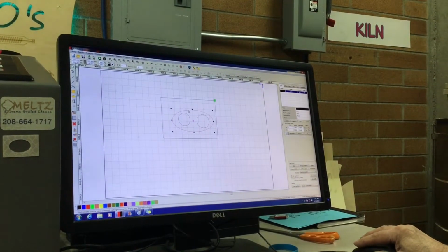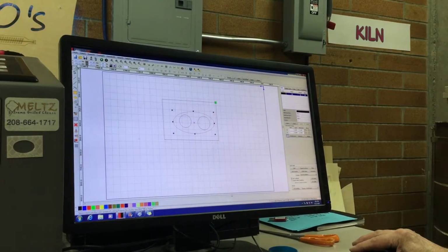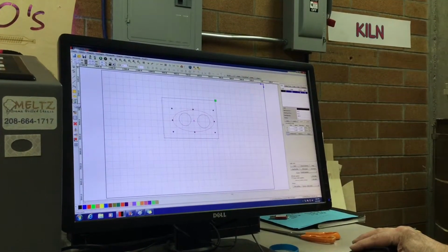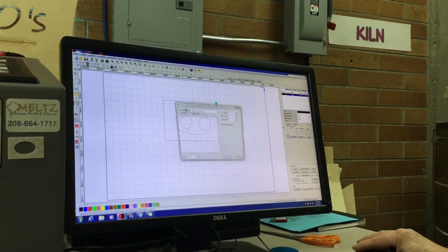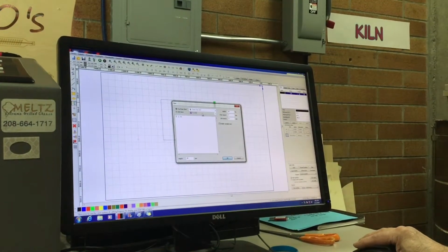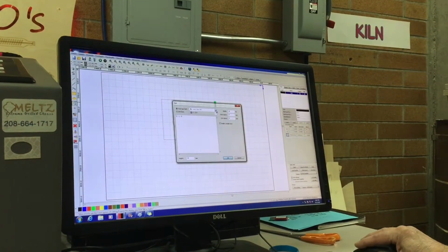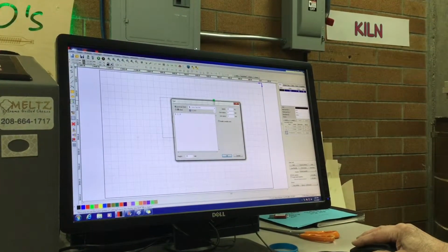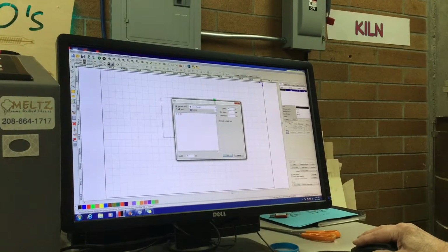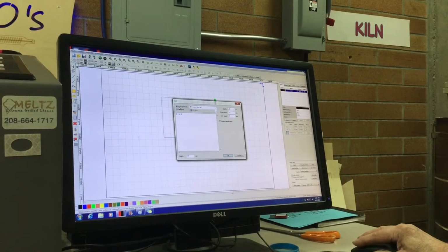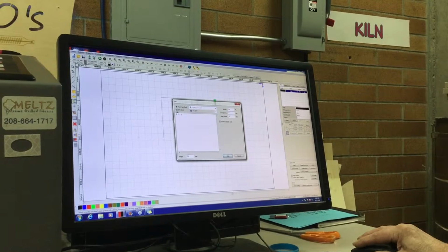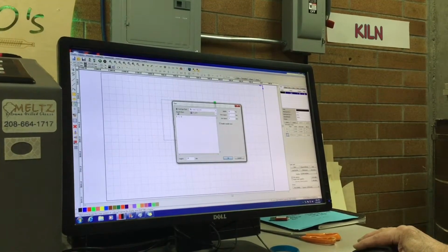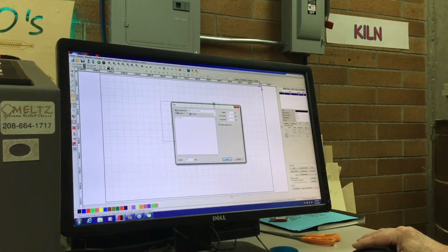So if you want to put some text in, you can click on the text box over here, click someplace out here on the drawing, and you get to choose a font from here. We're selecting TrueType fonts right now. Any TrueType font will work as long as it's loaded into the machine system. We rarely use the SHX font because TrueType covers so much.